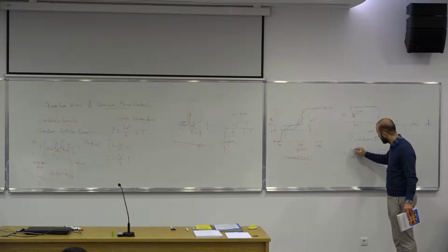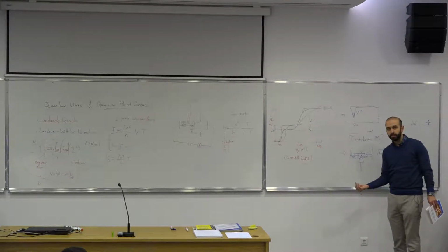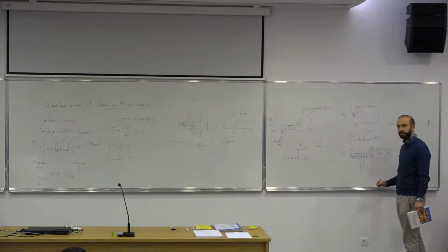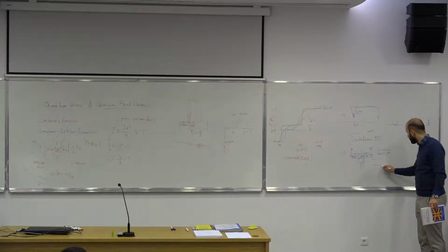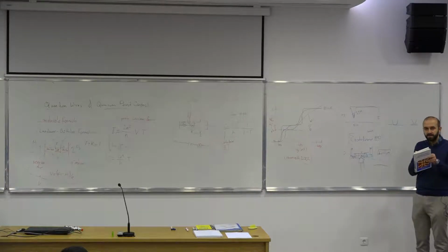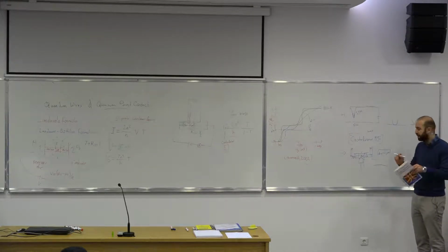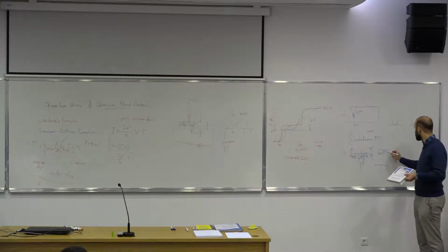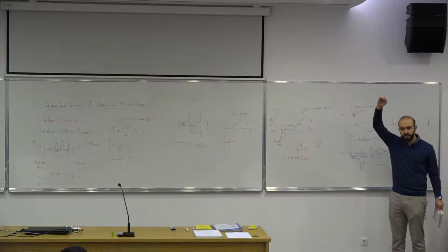Then what you do is you have some fixtures here, and then you have a manipulator that can push from the bottom. So these are fixtures, okay, these are fixed, and then you push from the bottom. As you push, this whole thing will start flexing, and as it flexes, it will start pulling apart this gold or whatever, palladium film or platinum film. As it starts pulling, of course, you have to use a piezoelectric pusher and be very gentle with it. As you pull it apart, at some point, you'll end up with something that is very, very sharp. Of course, if you measure the conductance versus the piezo position, you can see the steps forming again.